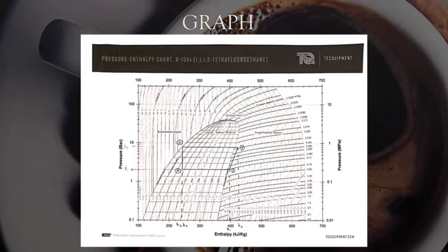So from process 4 to 1, which is the evaporator, here the refrigerant is cooler than the refrigeration chamber. Thus, heat travels naturally from the cooling chamber to the evaporator, whereby heat absorption happens. This causes the refrigerant to evaporate. So from this P-h diagram, we need to get the value for the enthalpy to fill in Table 2, which is the enthalpy table.